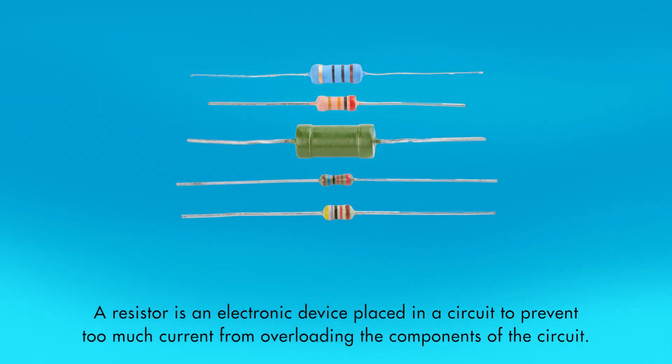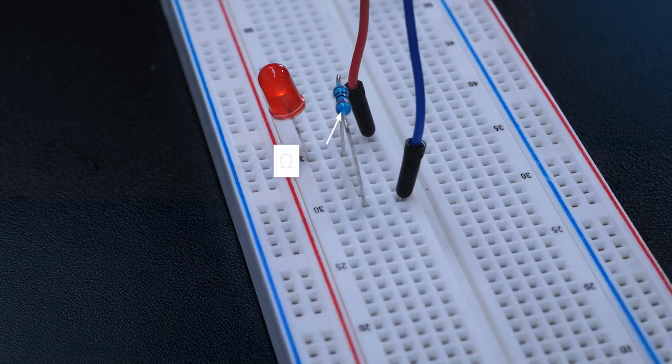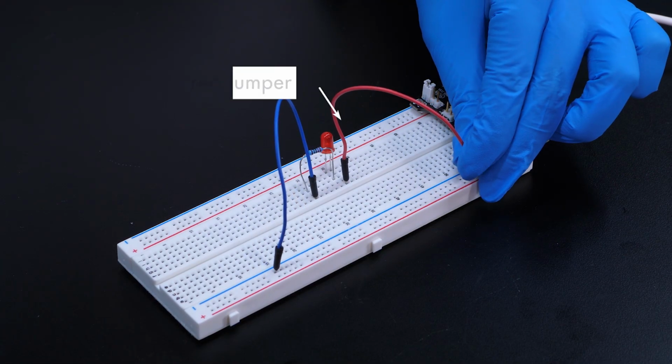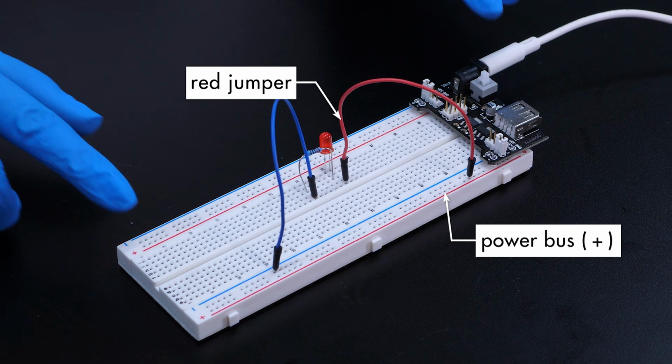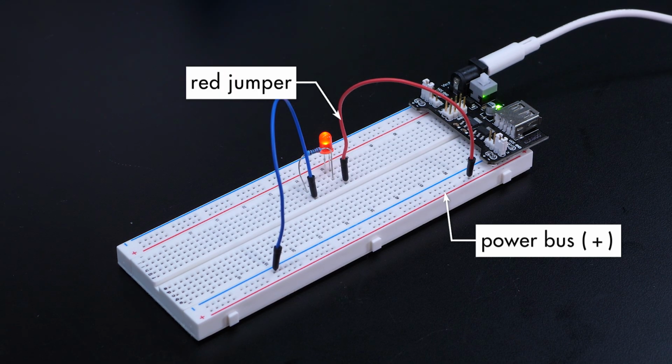A resistor is an electronic device placed in a circuit to prevent too much current from overloading the components of the circuit. An LED cannot handle much current, so a resistor is placed in the circuit to control the amount of current that flows through the device. The resistor in our circuit provides 220 ohms of resistance. From the LED, a red jumper returns electrons to the positive power bus, thus completing the circuit.